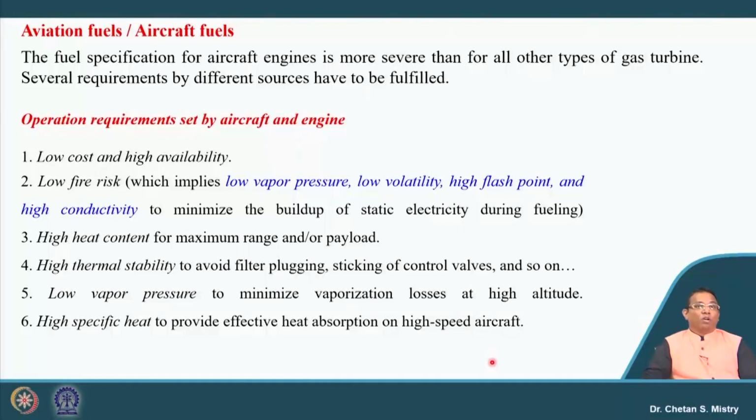Okay. Now, let us see what all the requirements are that are set by the aircraft and engine. So, what it says is, we need to have this fuel available at low cost and high availability, low fire risk. So, the properties it should have are low vapor pressure, low volatility, high flash point, higher conductivity, which will minimize the buildup of static energy during fueling.